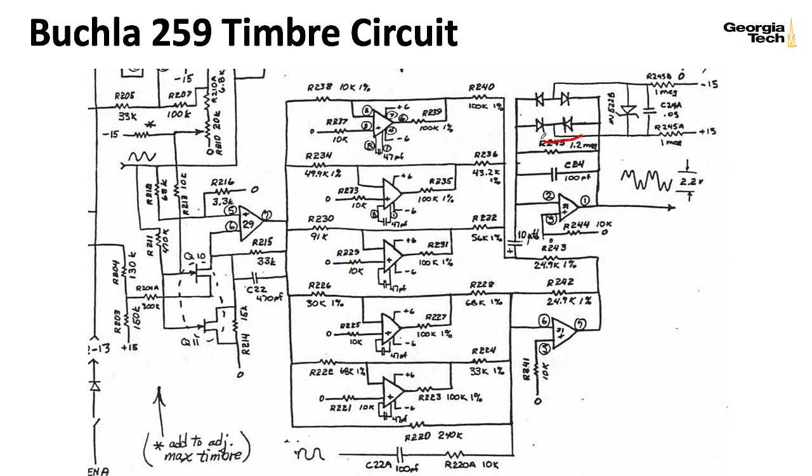We also have some interesting circuitry up here, and these are basically designed to operate as voltage clamps at extreme voltages. And in this example output that Don kindly drew here, you can see the effect of the sinusoid being folded back in on itself. I probably should also let you know that Buchla hardwired the 259, and for that matter the music easel, to take its input from the output of a triangle to sinusoid wave shaper.